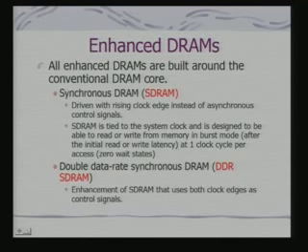So, you do not need what are called wait states, because if RAS and CAS are asynchronous signals generated by the memory controller, the time taken to get the data would be more than the bus clock, the clock at which the system operates. So, the system would need to wait to get the data from the DRAM, and that is why wait states can get inserted. But if these RAMs can be synchronized with the bus clock or the system clock, then the wait state requirement can be eliminated, and that is the basic motivation of designing the synchronous DRAM.